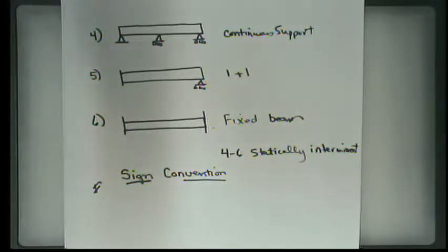So the sign convention becomes excruciatingly important. For moments, we've discussed the fact that clockwise moments are negative, counterclockwise moments are positive. And the reason for that is it corresponds to the right-hand rule, and also to cross products of vectors, which is really what a moment is.